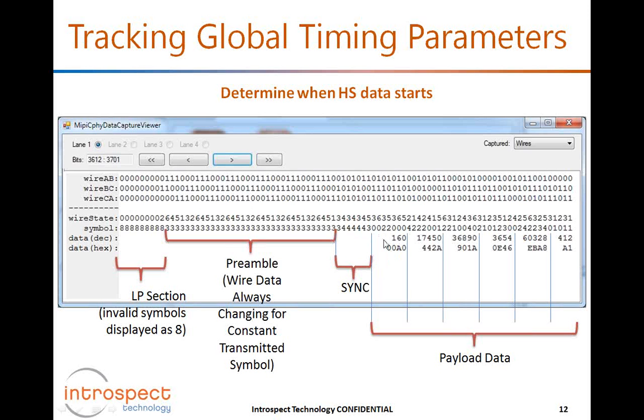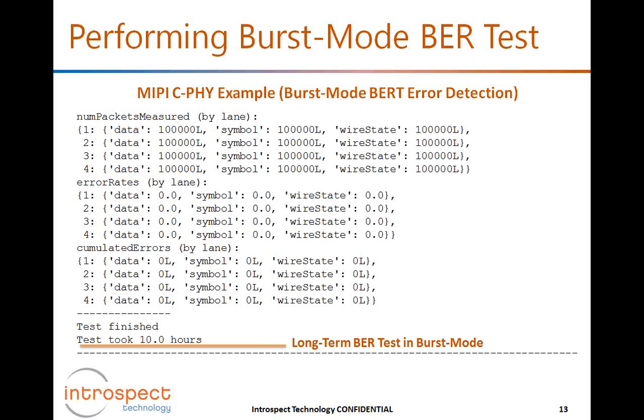And then the last topic for transmitter testing is that high-speed MIPI standards and mobile standards in general, because they are based on SerDes and because of the very high data rates that are sustained, have now also introduced the concept of BER testing, just like on conventional SerDes technology like PCI Express or SATA. And so one of the things that the MIPI standard has is BER testing, and this is an example of how one can perform long-term BER tests.